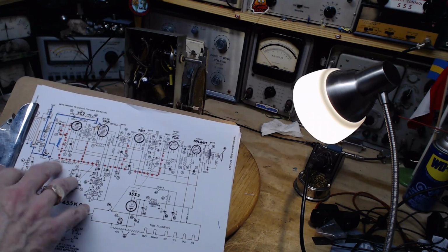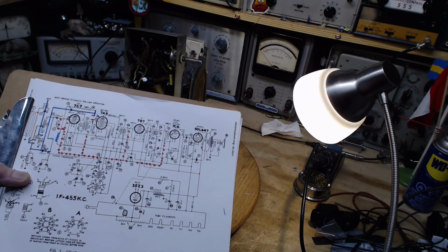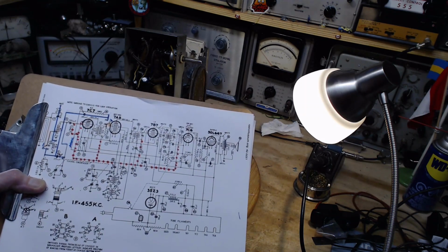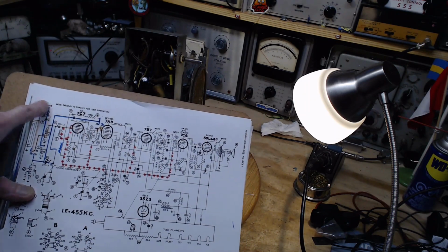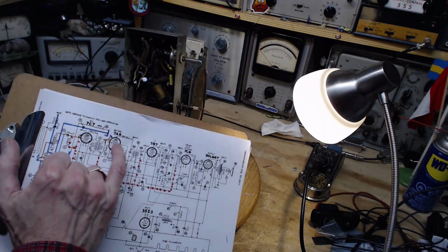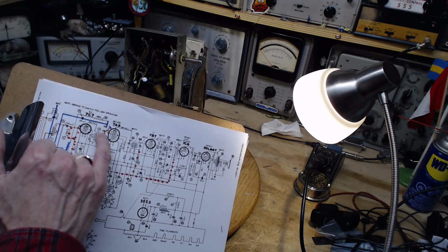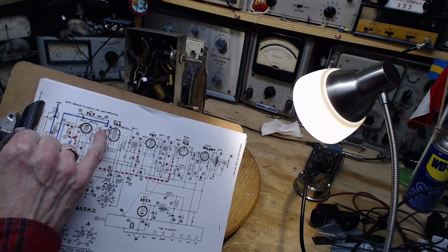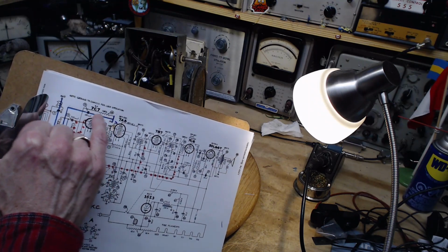So I spent yesterday looking at the surprisingly complicated arrangement in here, and it just became a little bit too much for me, along with many distractions I had yesterday. So I came in this morning and said to myself, look, the shortwave antenna signal has to get from this point to this point. When you flip to shortwave, this switch flips. This tube gets its grid supply from this blue line here, and all of this just sits here. Maybe it's doing something, but it's not affecting the rest of the radio because it's open circuited here. So if we work our way back, we just follow the blue.